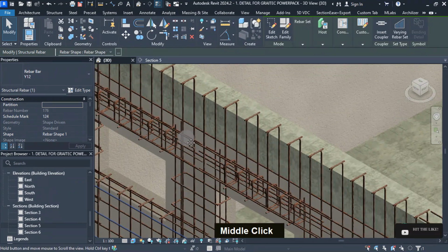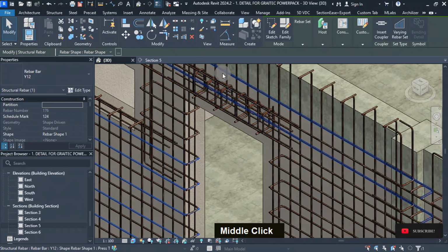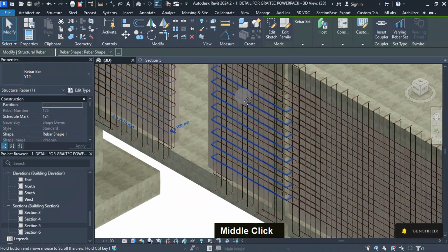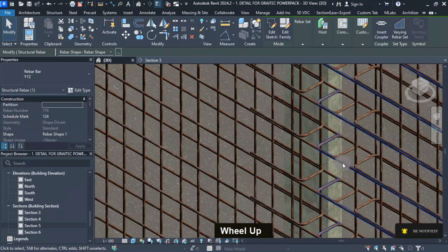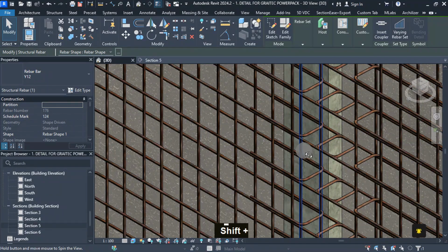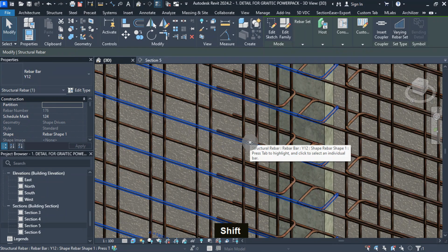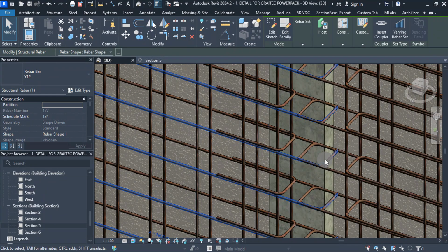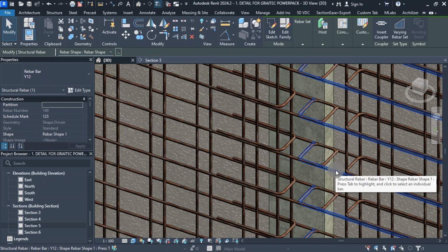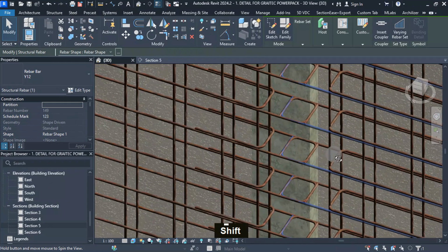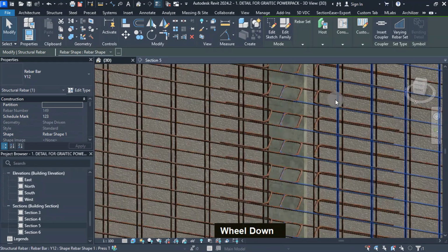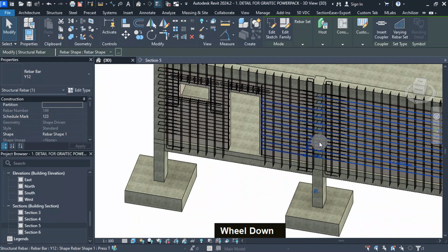To edit the lintel bars, we will utilize the opening bars command. I can zoom to this column to show you how the bars have been linked with the given parameter values. If I select on this horizontal rebar set, you can see how it has been placed and it ends at this point here. If I select on this other wall rebar set, it overlaps the previous rebar to this point within the column. This configuration forms a ringed shape within the column as seen.